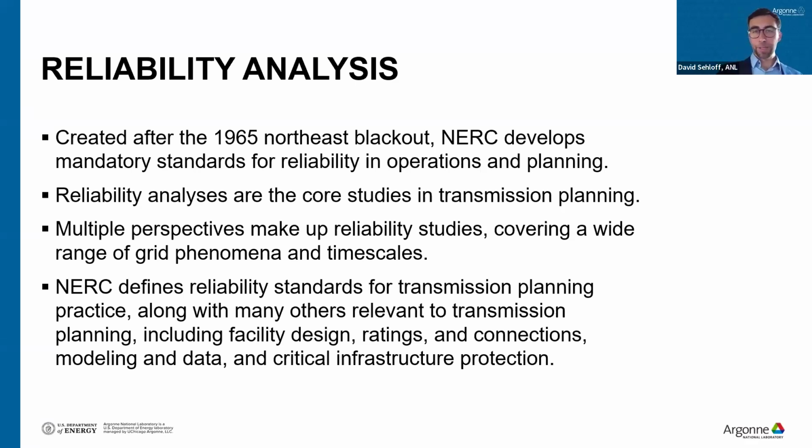So NERC has reliability standards for transmission planning practice specifically, but there are also a lot that are relevant to transmission planning. So this includes facility design ratings and connections, modeling and data and assumptions, and also critical infrastructure protection. We'll focus here on the ones that are specifically for transmission planning practice.